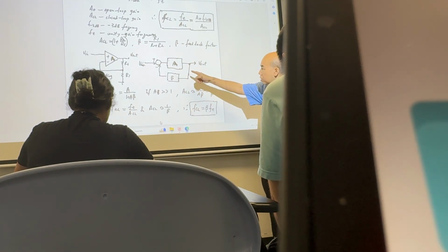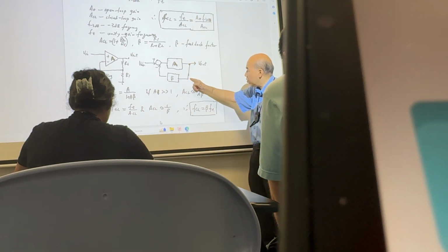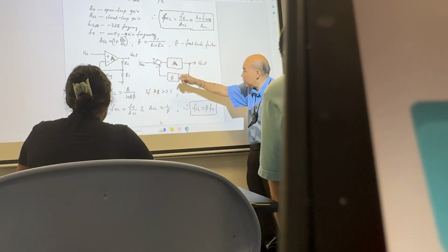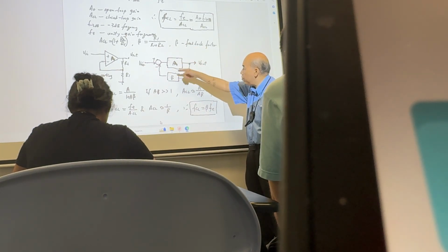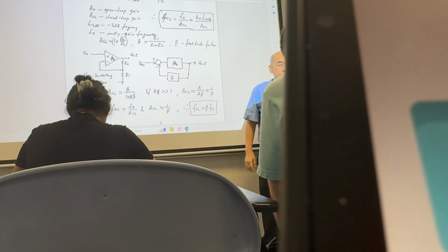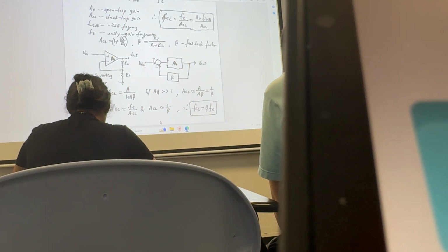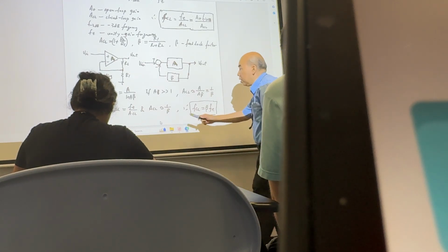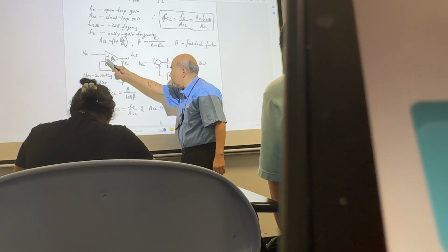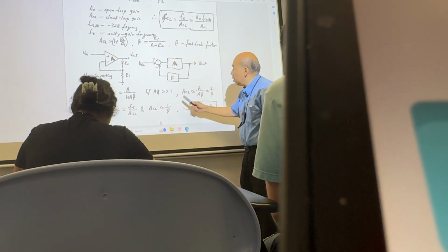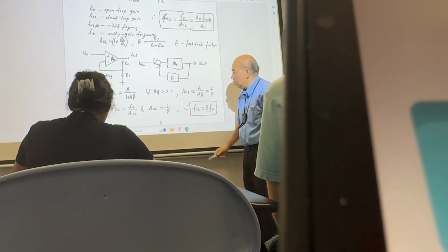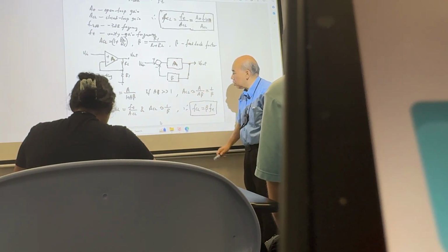You can see that this control concept has an open loop gain, and then you have a feedback network, and then the difference in the input. Beta is the feedback factor. The feedback factor samples your output and feeds back a fraction of your output to the negative input, not the positive input, right? It's a negative feedback. If you put it in the positive terminal, the negative will not work. The negative is a negative feedback, right? Now this is a model using the op-amp to prove it. Using control concepts, you can prove it.